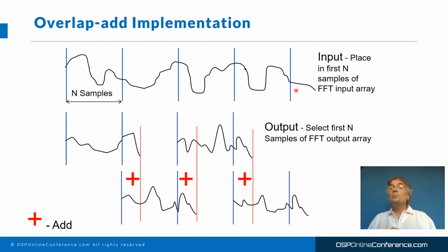Now, there is one other point that's worth mentioning because of this. The question to pose is, what size fast Fourier transform do we require in that application? There's a note about it in the slide. Basically, the key thing to remember is that the fast Fourier transform length must be greater than n plus m minus 1.